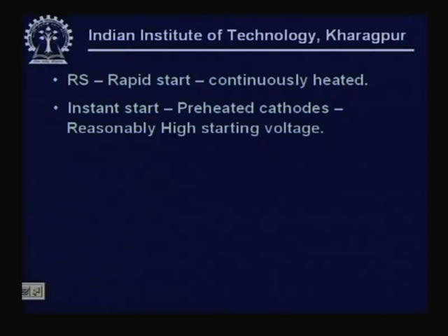This is achieved by having the heaters placed at the two ends and special cathode elements that are used, together with small amounts of ionizing rare gases, so that the ionization potential is low and quickly enables the lamp to go into discharge mode.